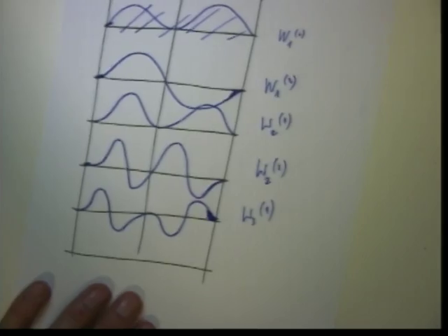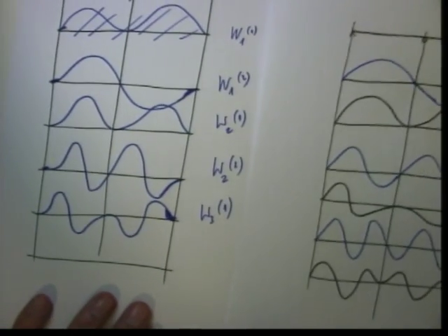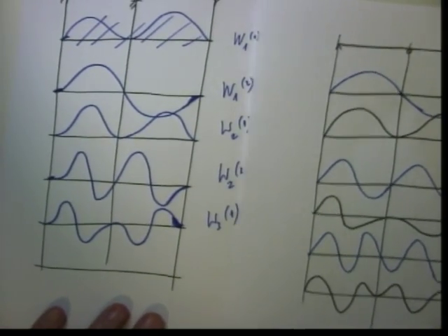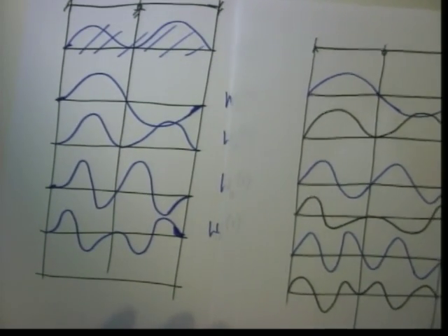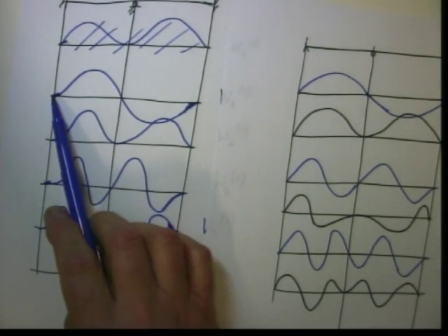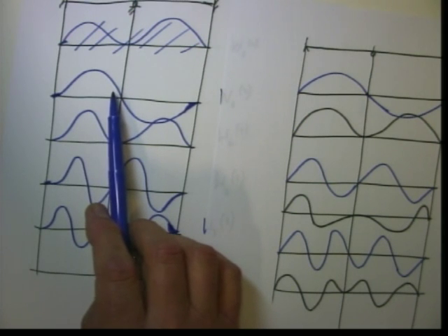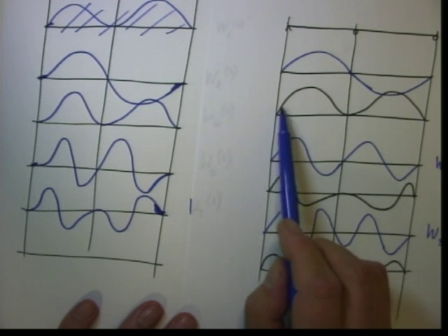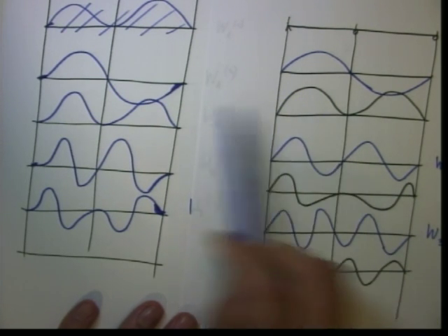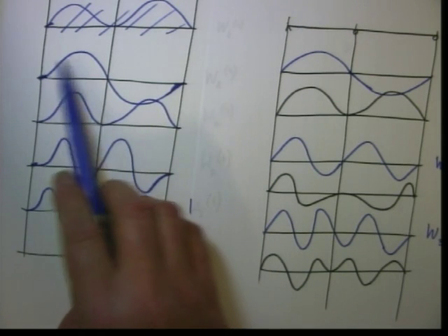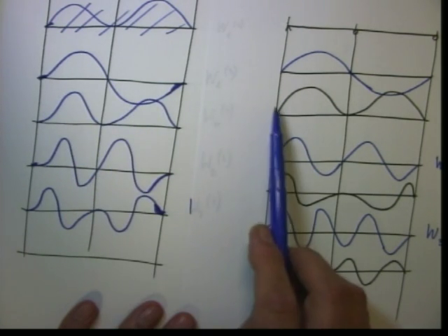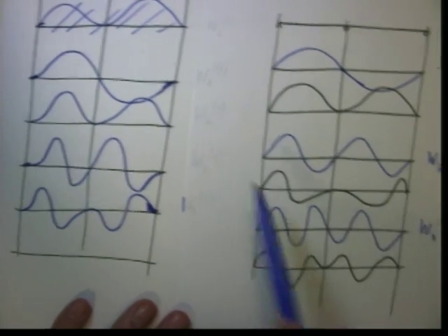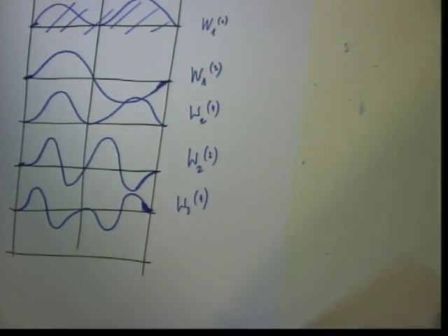Now if you compare, now we will try to compare somehow. Okay, this mode shape, clamped, simply supported. And here we have clamped, simply supported. So this is actually, if you cut and paste, you will see absolutely the same pattern here. That is clamped, simply supported. That is clamped here, simply supported there. So that is why they share the same frequencies. The mode shapes are the same, actually.